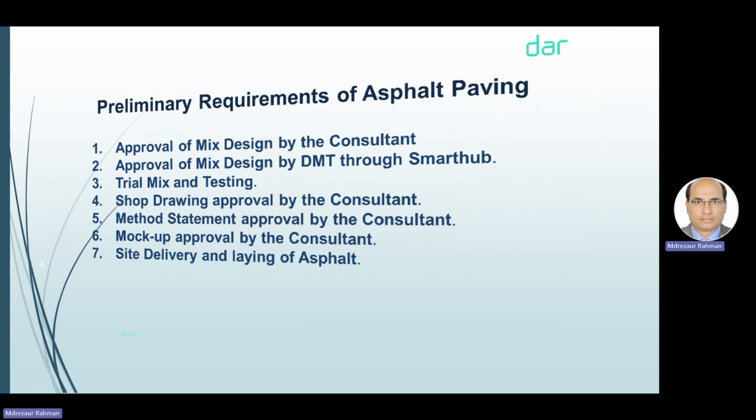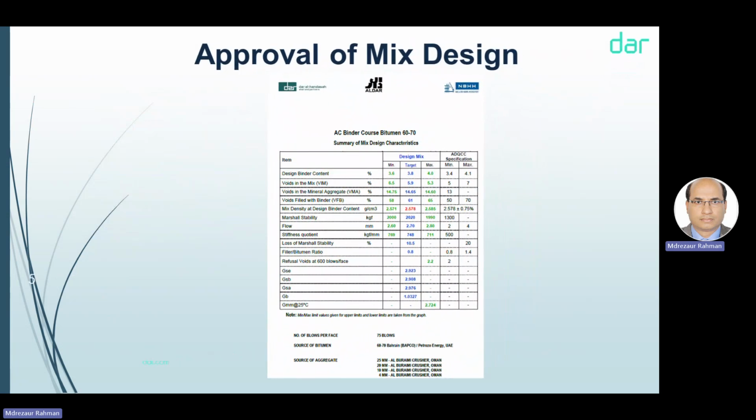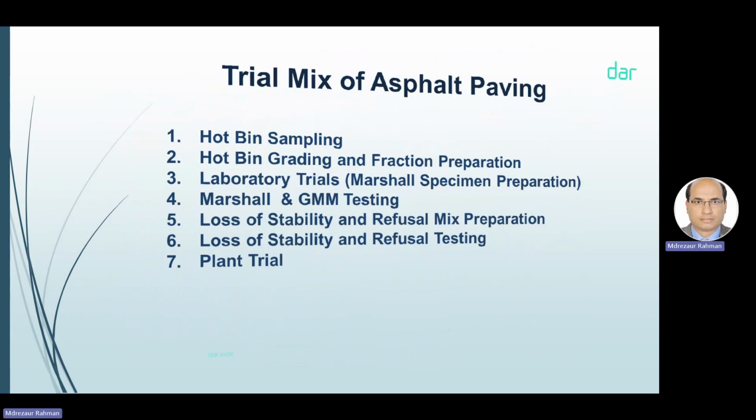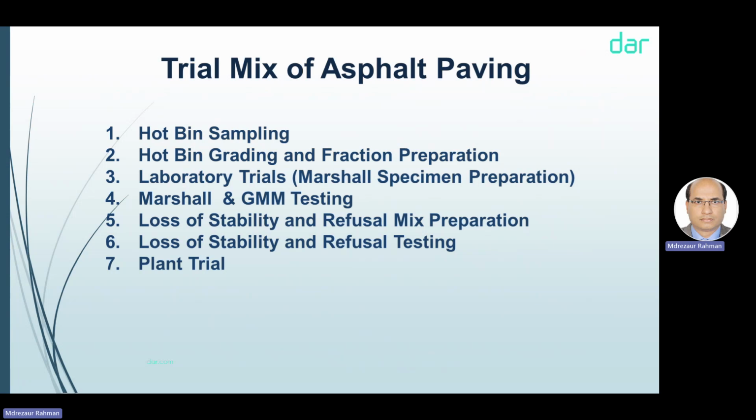If you have any questions or anything, you can add. Okay, this is a sample of mix design. As I told you before, first the contractor should prepare the schedule. This is a typical mix design for our state project. This mix design has to be submitted to the consultant. The consultant should review and approve or reject based on the review points. Basically, this is a design summary. If the mix design is okay, then we have to go for asphalt mix.